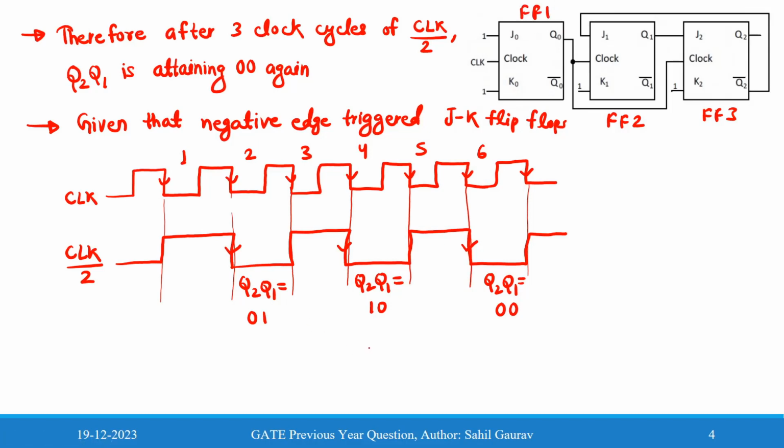One thing you should also note is that for flip-flop 1, both the inputs are 1 1, so it is always in toggle condition. So the Q0 is always 0. So at this sixth clock pulse we get Q2, Q1, Q0 as 0 0 0.